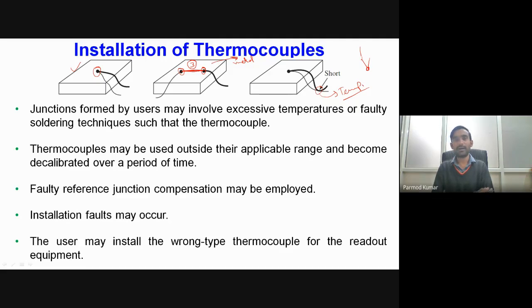If we are using two different thermocouples from the same roll of wire, and our sole purpose is only to measure the temperature difference between these two values, then we need not worry much about the errors, because we are mainly interested in the difference between two points. Whatever error is associated with the first point, almost the same amount of error will be associated with the second point. So in that case, we will have less inequality in our measurement.